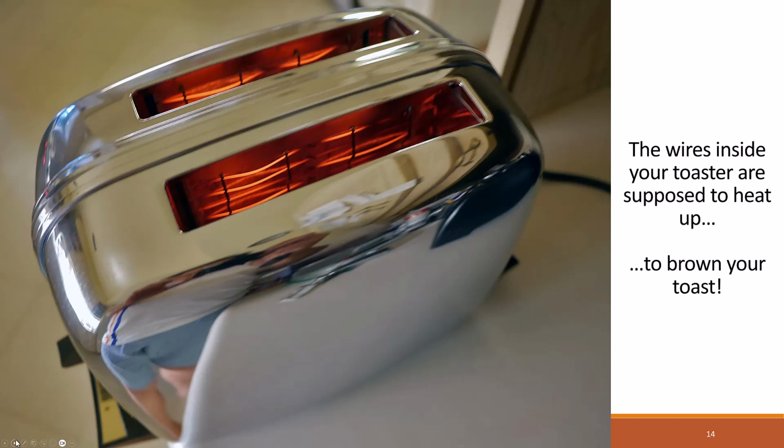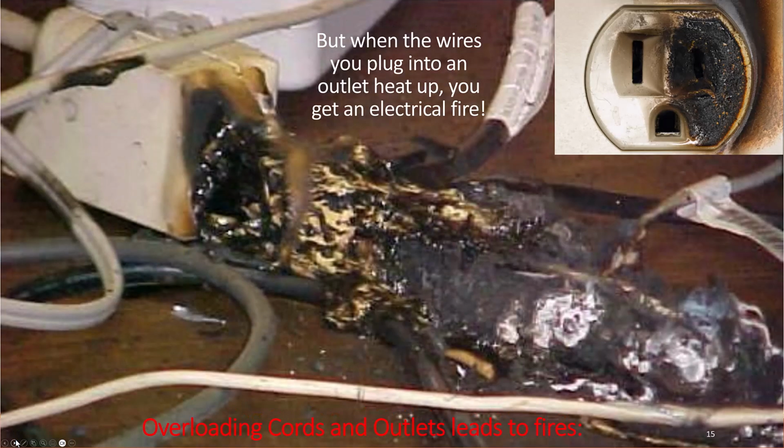But when you come to puny little extension cords that you hook up to that outlet, those things can start heating up and cause an electrical fire, and never quite trip the breaker until it's too late, because those puny wires are just not consuming as much electricity as they arc between each other as the insulation melts and breaks down and allows the 2 wires or 3 wires to arc against each other. So overloading cords and outlets can lead to fires. And that's what the arc fault circuit interrupters, AFCIs, protect against.